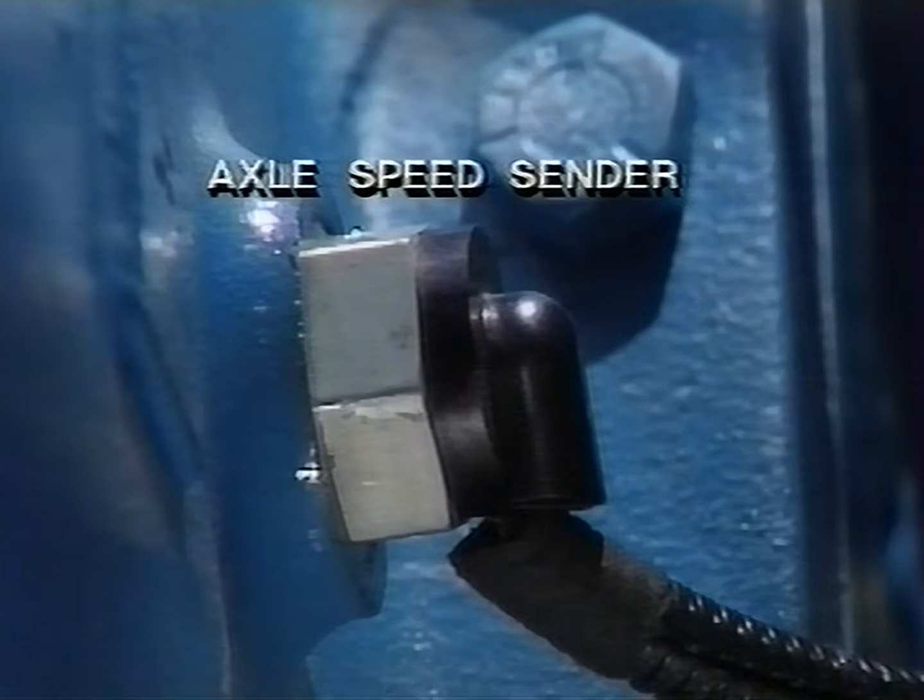On the opposite side of the transmission, from the transmission input devices, is the axle speed sender. The sender uses a pickup coil close to the front wheel assist gear coupling. The action of the gear close to the pickup creates pulses which are relayed to the EIP. The EIP converts the frequency of the pulses into ground speed.